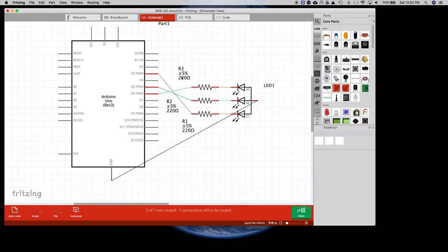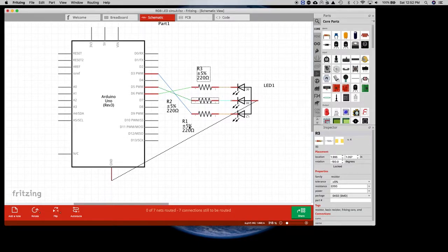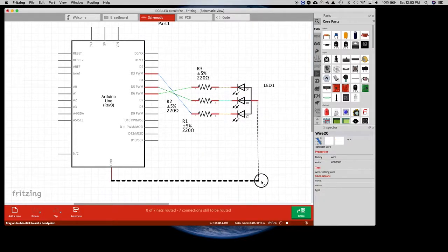That looks much better. Now, as you may recall from the written lesson, circuit diagrams should be as simple and clean and clear as possible. So the next thing we want to do is clean up these wires and make sure that they're not just going over any elements or components if we can avoid it, and also try to have horizontal and vertical lines only where we can. So to do that, you can just drag things around. And it can be a little finicky, but it does work.